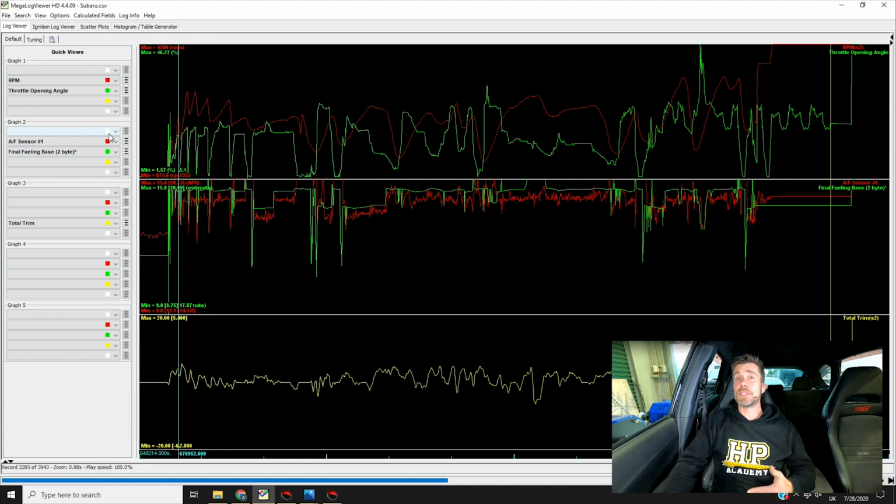Nothing wrong with doing this for the closed loop portion of your operation. As I've already dealt with here, generally it's not going to be super accurate for wide open throttle operation. So if you are bringing a wideband in, then it would make sense to just use that for all of your tuning. A little tip here as well is the scaling.